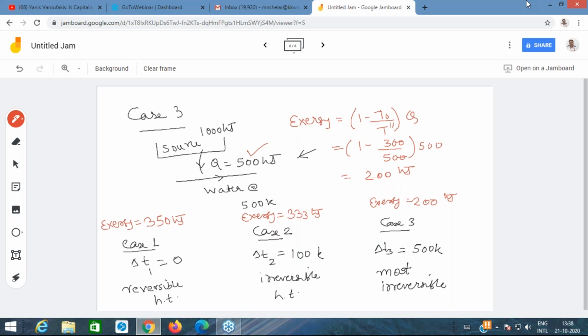So why is that important? That is important because the work potential of the heat would decrease as the temperature is decreased. The exergy, or the maximum work potential, is obtainable if the heat is of highest grade. And when is the heat of highest grade? When it is at higher temperature, right?